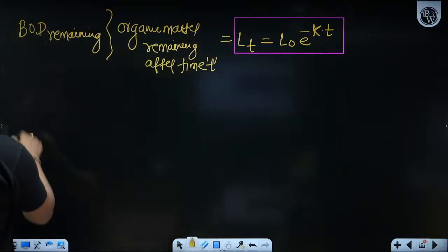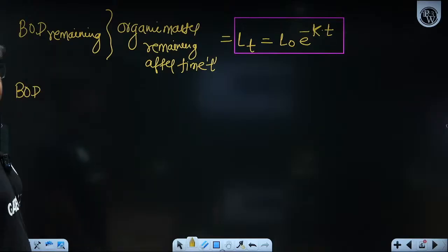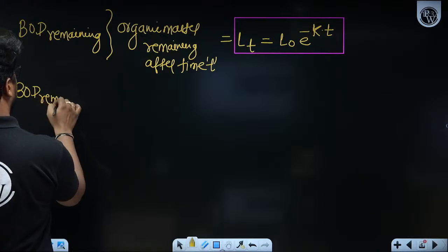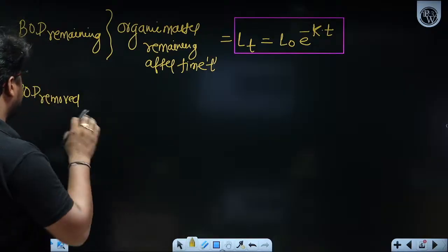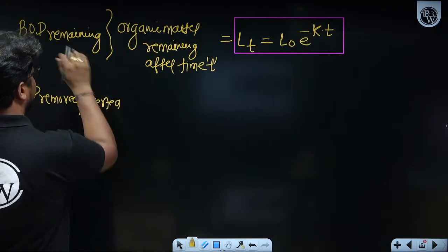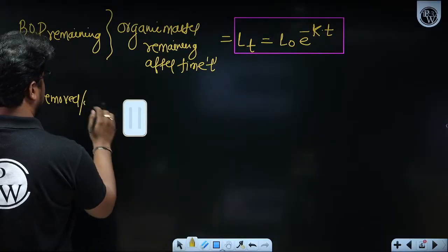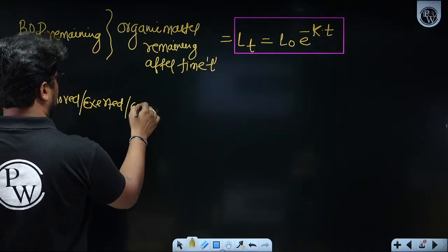Second thing, they will ask you to find out BOD. Sometimes we also call this BOD removed, or sometimes they will simply say BOD. BOD means BOD removed they are talking about. If they want you to find out BOD remaining, they will mention in that question exerted or consumed.